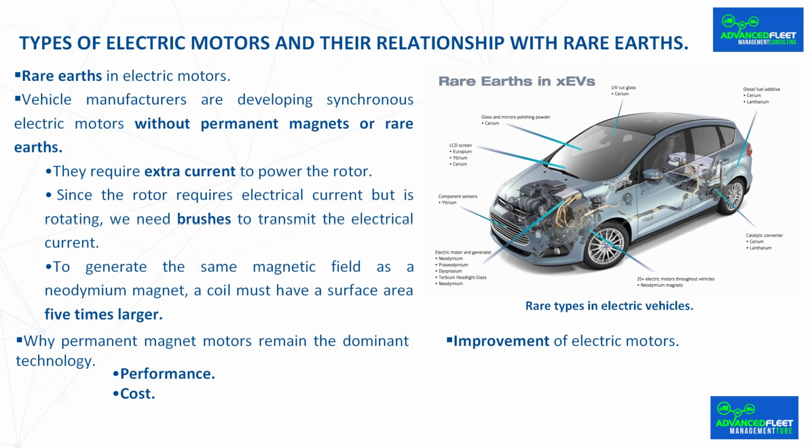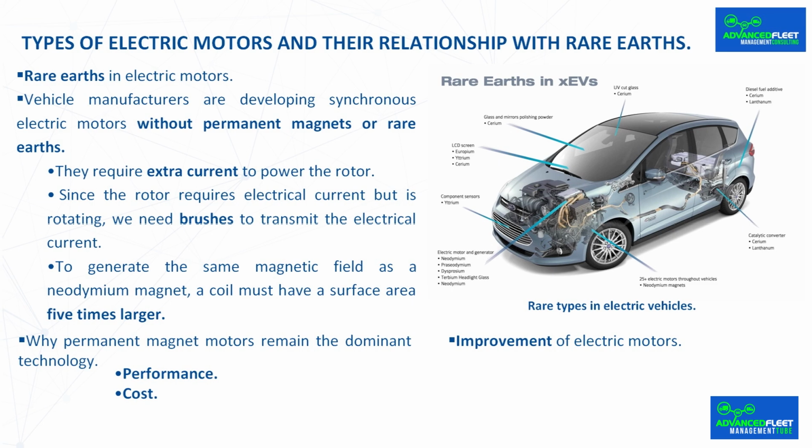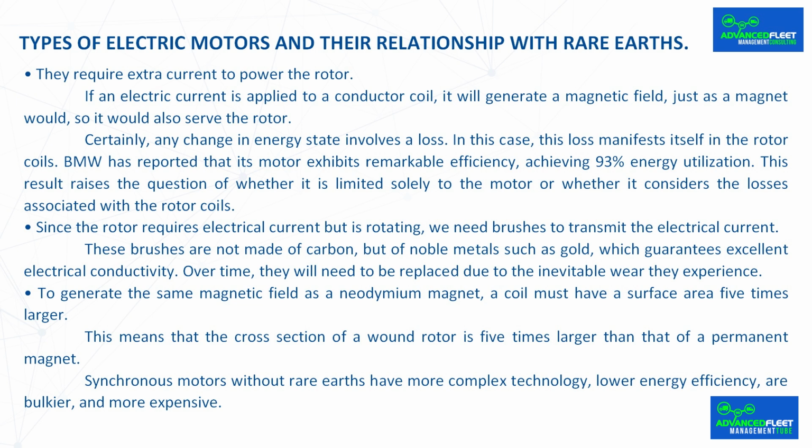Vehicle manufacturers are developing synchronous electric motors without permanent magnets or rare earths. This represents a significant innovation in the sector. However, it is important to note that this development entails three aspects that must be considered. They require extra current to power the rotor. If an electric current is applied to a conductor coil, it will generate a magnetic field, just as a magnet would, so it would also serve the rotor.